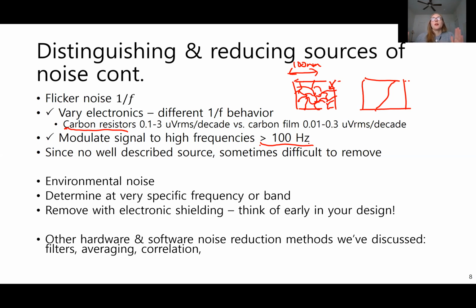There's not a time dependent process taking place there. It's just going to be more and more electrons being produced in your resistor with the thermal noise. So if you do ensemble averaging with thermal noise, it's just going to keep increasing, but the time dependence of the shot noise lets you average it out. Okay, thank you.